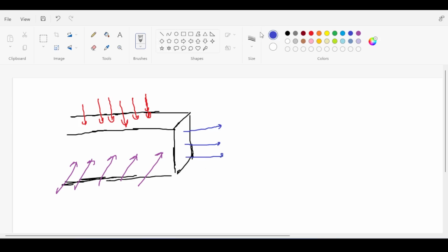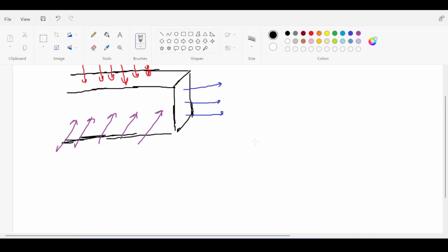Now, from those loadings that are applied on the beam, you will have moments and shear and whatnot. So allow me to draw you another beam where I want to discuss the shear and moment that you would get on the beam. On the beam, you have 3 moments and you have 3 forces as internal forces. You have an internal force in the axial direction, and of course, that's called an axial load or axial force.